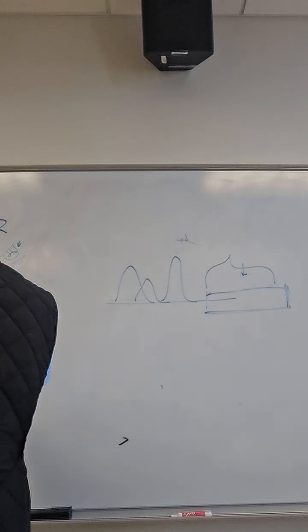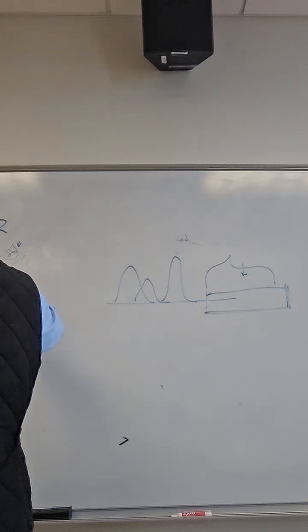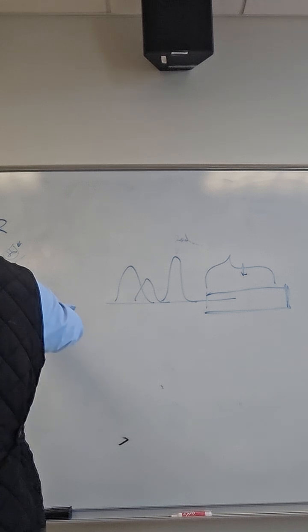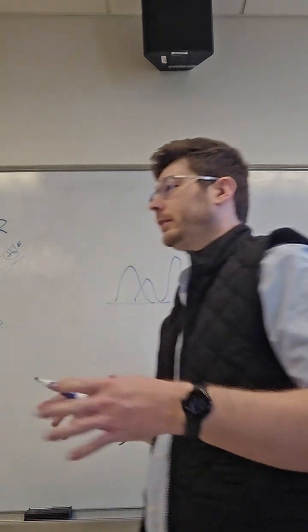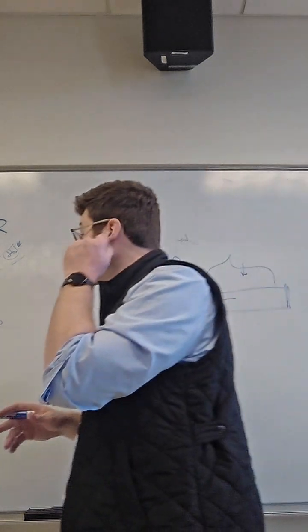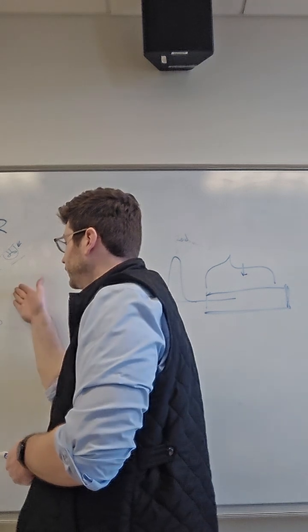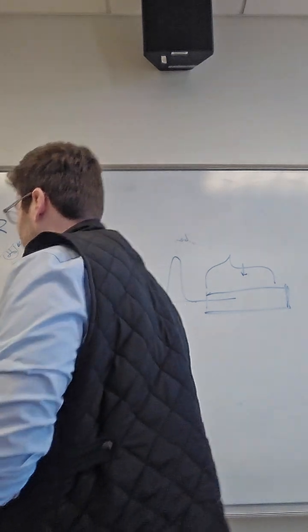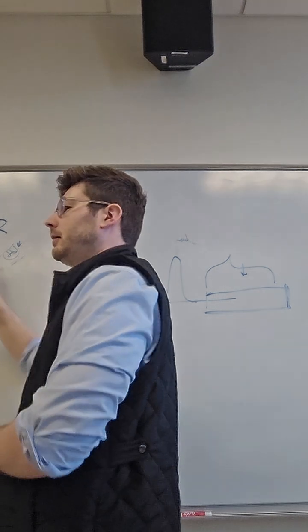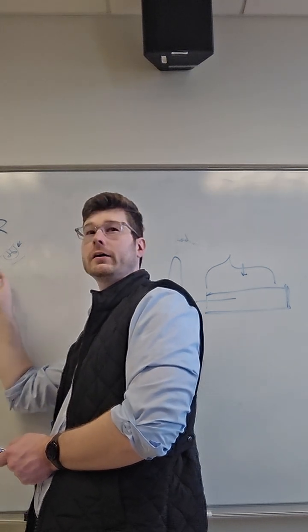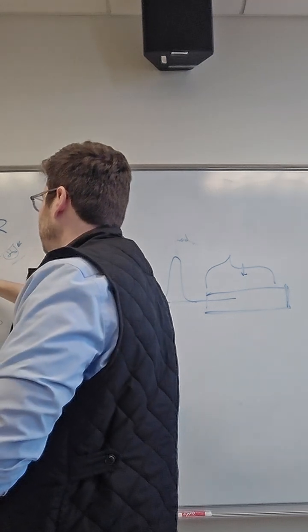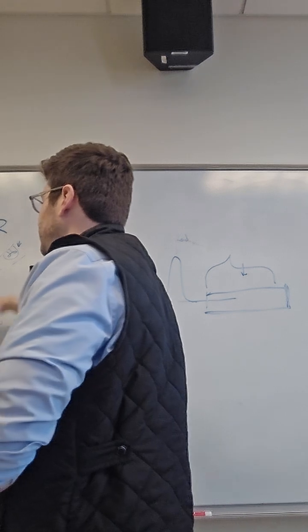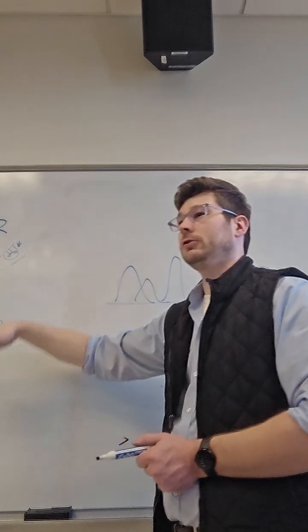Okay, so the cool thing about this is that we can see or know how much light this should be putting off and how much light we should be receiving. Okay, so again, we have our baseline, how much should we be receiving? If it's a distance sensor and the thing that we're sensing is infinitely far away, we're probably not going to get any IR back, or we'll expect to get no IR back, right? But if something is right up front, if we're holding a mirror to it, practically, we would expect to see almost the full intensity of that IR reflecting back. And then we can do a lot of interesting things with that.